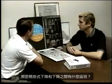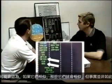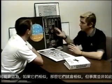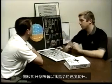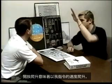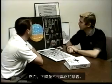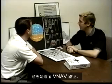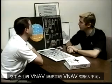Then what would be the difference between open descent and descent? Actually, it's a real big difference. You'd think that if these were similar, these would be, but they're not. Open descent is similar to the open climb thing. Open climb means climb at whatever speed I have commanded. Open descent means descend at whatever speed I have commanded. Descent, though, doesn't really mean that. It means follow a VNAV path. And VNAV in Airbus is very different than VNAV in Boeing.